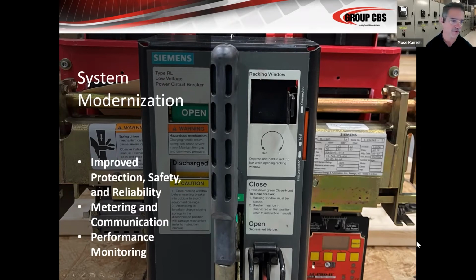But in particular, I want to point out here in the bottom right corner, this breaker, which probably was originally built with a static trip unit, I'm going to say a solid state trip unit, really good in the day, but those are notoriously failing on a more regular basis. And so once again, we take the opportunity to upgrade that. In this picture here is an AC Pro 2. And what's special about an AC Pro 2?